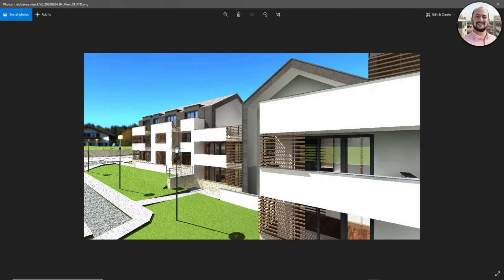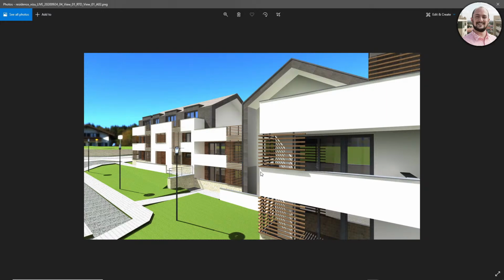I like this result and I'm willing to wait for the quick render. And so the quick render looks like this. It's actually removing a lot of the noise from the real-time rendering, which is only for work, not for the clients. So this is already having nice features, but still I can see a few places where a little bit of noise is introduced, especially around corners. Some corners are actually just not very visible, as you can see here. So if I would like to make them more emphasized, I can increase the quality, and I can use the detailed render.